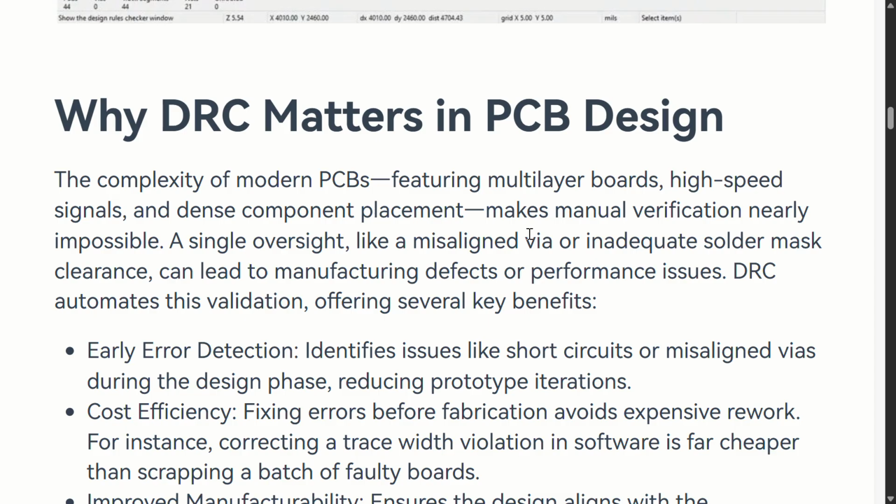So following those minimum clearance rules, you can. But if you want to make it even denser, it's not allowed, because it will violate the DRCs, the design rule check. Those rules and regulations will be violated, which will cause a DRC validation error. During DRC validation, it will throw an error. So you can pack components as close as you want, but you still need to abide by the DRC rules.